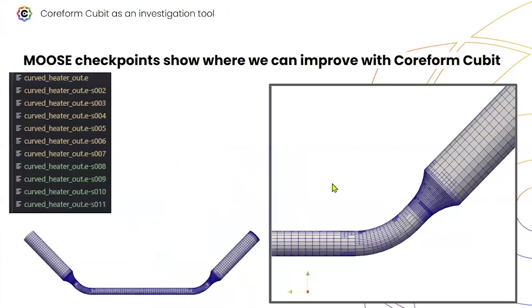So if I didn't understand electromagnetism, or how heat worked through one of these heaters, and I didn't quite know where to put the nodes, I can start the program with the auto mesher, let it create one or two of these meshes, and then see, okay, this corner is thermally interesting or electrically interesting. And then it may be faster for me to remove nodes in places that aren't interesting and put more nodes here instead of waiting for the auto mesher to do it.